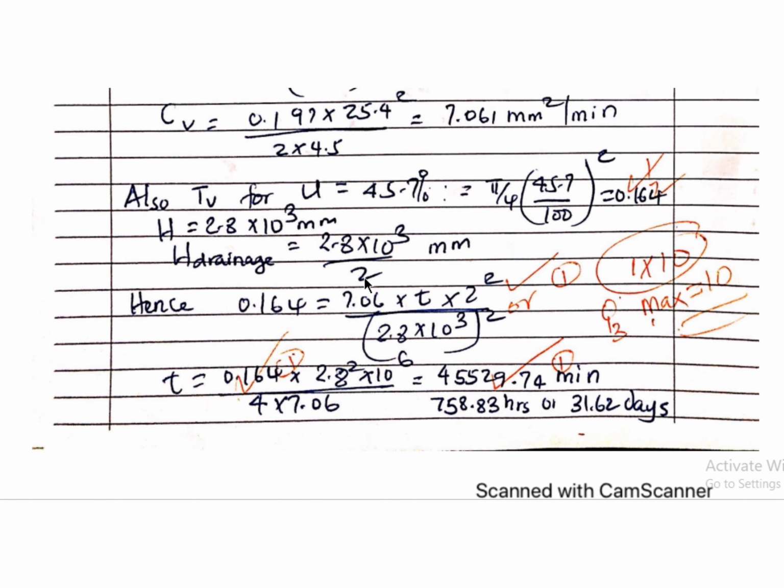In the experiment, you know the time, but the thicknesses are different, right? So the experimental values are helping us to get things like Cc and Cv. The time in the laboratory we know, so based on the time and the changes in the laboratory, we can use that to get Cv. But in the field, we don't know the time, but we have parameters from the lab. So we know Cv and the thickness. Again, we substitute in this formula.